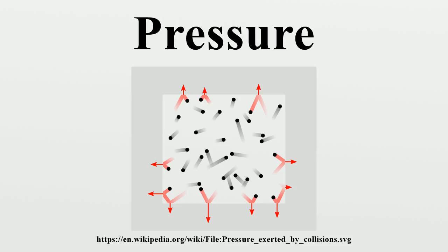Water is non-toxic and readily available, while mercury's high density allows a shorter column to be used to measure a given pressure. The pressure exerted by a column of liquid of height h and density ρ is given by the hydrostatic pressure equation P = ρgh, where g is the gravitational acceleration. Fluid density and local gravity can vary from one reading to another depending on local factors, so the height of a fluid column does not define pressure precisely.